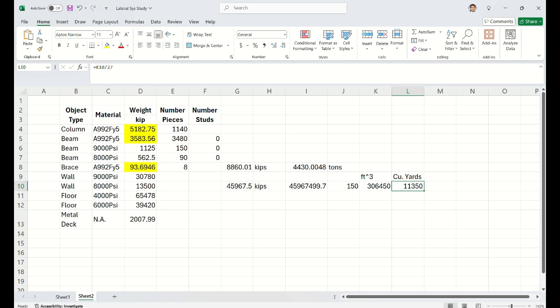But again, for your report, look at that old sample in the canvas. You may find out how they structure it. It depends on the team, but I want you to at least be aware of it because you need that in the construction industry. You want to prepare the bidding package, then you need to make sure what the steel tonnage is, right? In your bid package, you need to specify exactly the steel tonnage and concrete volume so that bidders use the right numbers. Otherwise, I think you guys are taking an estimation class, right? You calculate the material takeoff by hand manually. It's ridiculous.